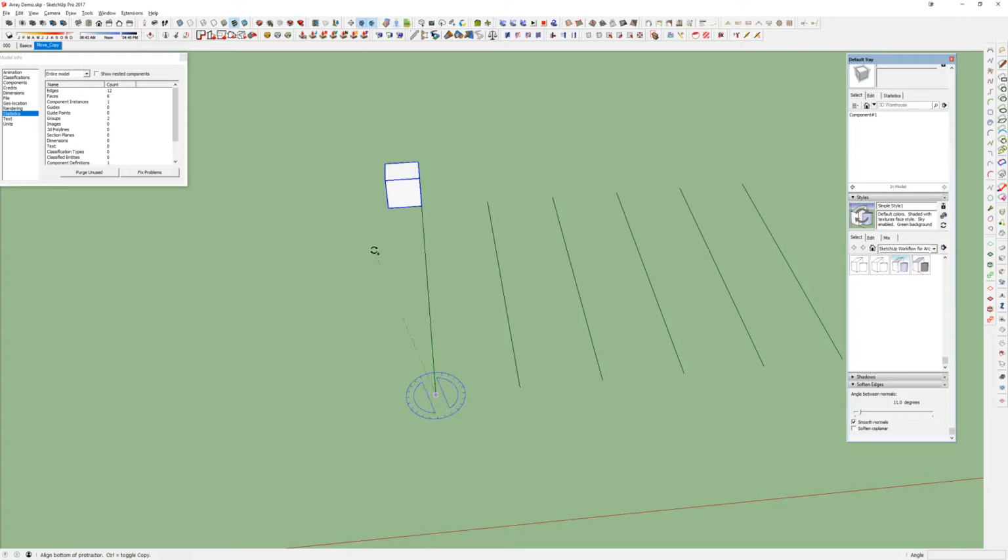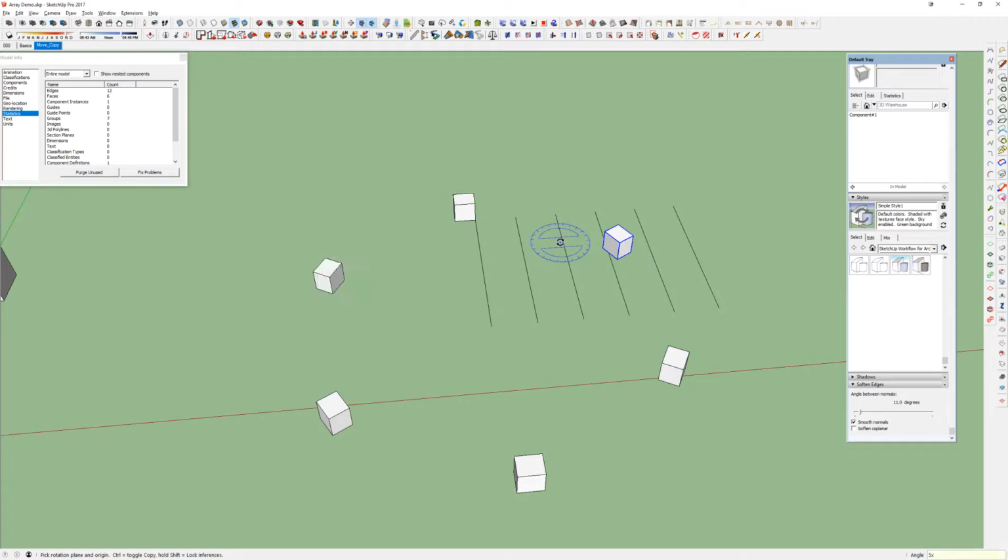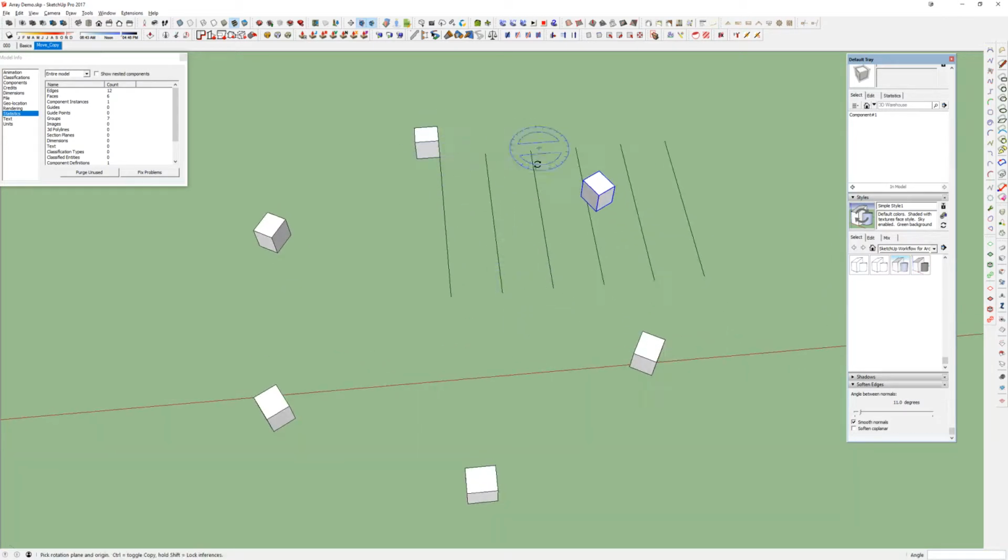Similarly, I can copy and say I want it 60 degrees, and then say I want a complete circle, which would be, what is that, 4? I'm sorry, whoops, 4x. Sorry, 5x. 5x would give me a complete circle. So that's 60, 120, 180, 240, 300, 360.